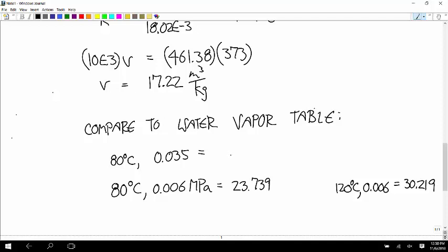That's the specific volume. 4.625. Oh yeah, it's vapor. So okay, 4.625. I have a bad habit of seeing water and thinking liquid, but for a liquid, changing the pressure doesn't have much of an effect on the specific volume. A vapor, you can smush pretty easily, so that specific volume can change a lot.